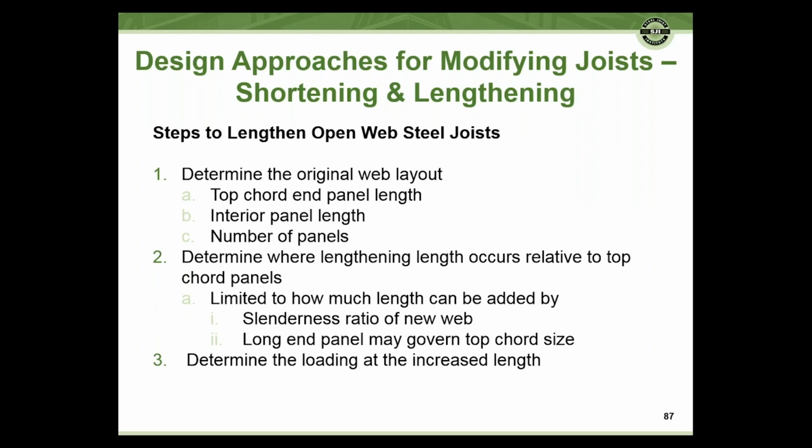The steps you want to go through for looking at lengthening open web or lengthening steel joists. Determine your original layout. What are your end panels, your interior panels? How many panels do you have? Where do you want to lengthen the joist? Again, if you can lengthen it, typically you want to do it at the very end of the joist, at an end panel.